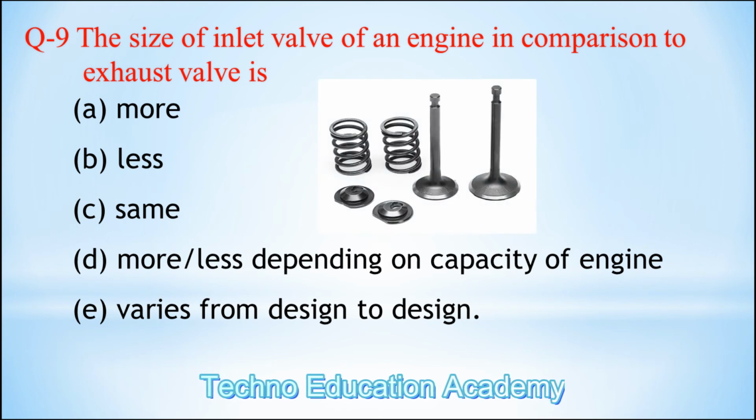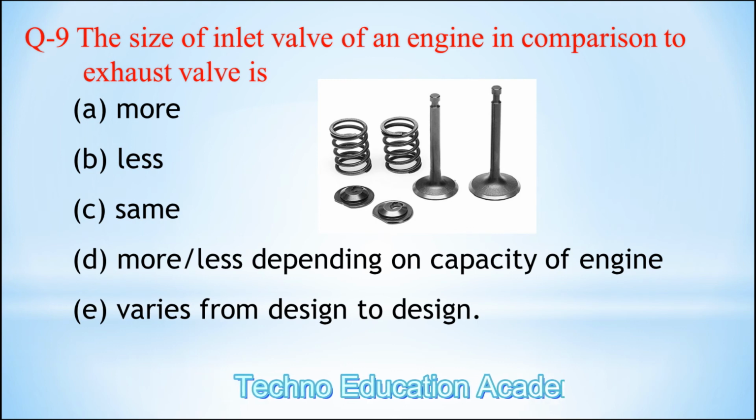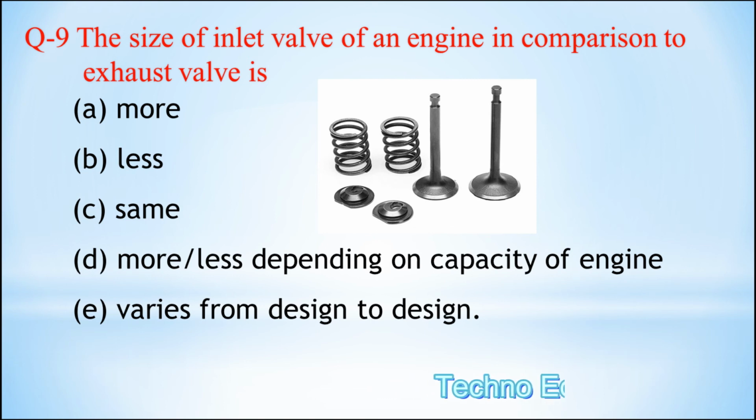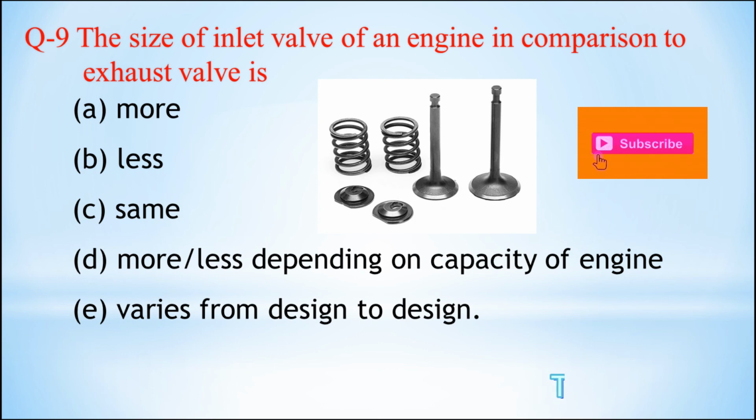Generally the size of the inlet valve is larger compared to the exhaust valve, because during the suction stroke negative pressure is present in the cylinder, so it allows more air into the cylinder and the combustion efficiency increases. During exhaust, the pressure of the exhaust gas is sufficient to escape from the exhaust valve.